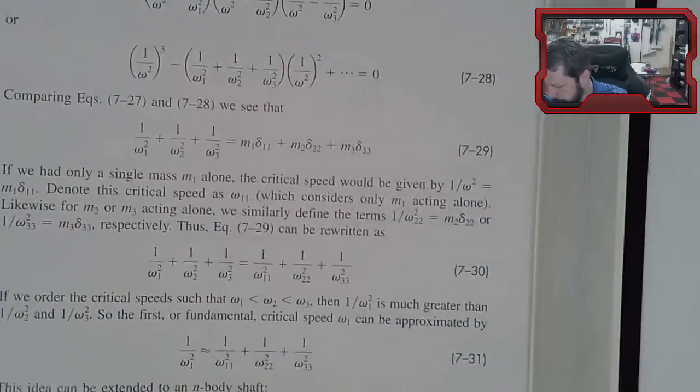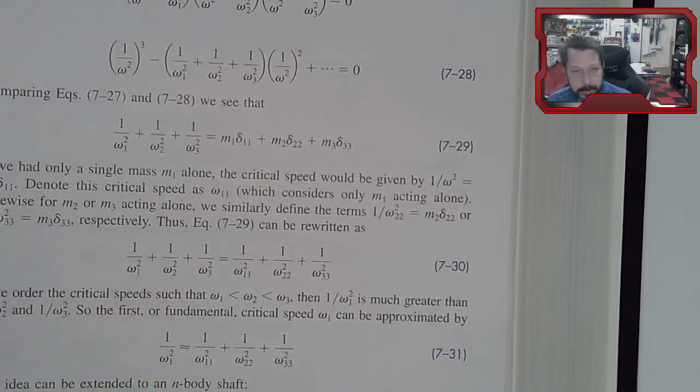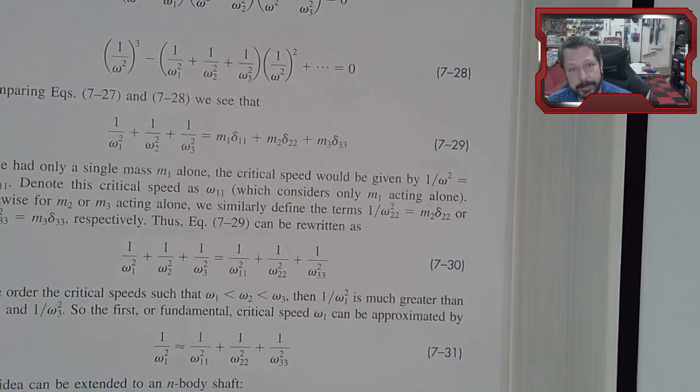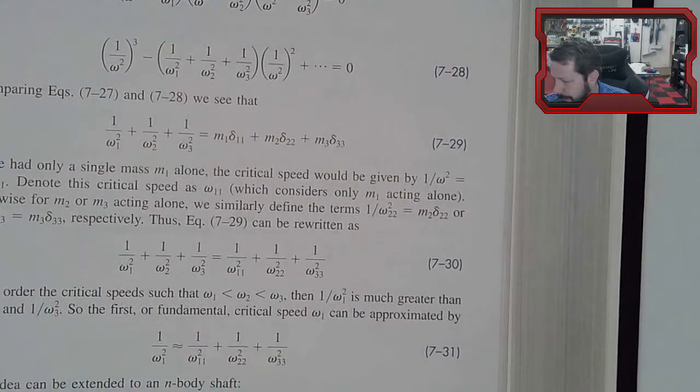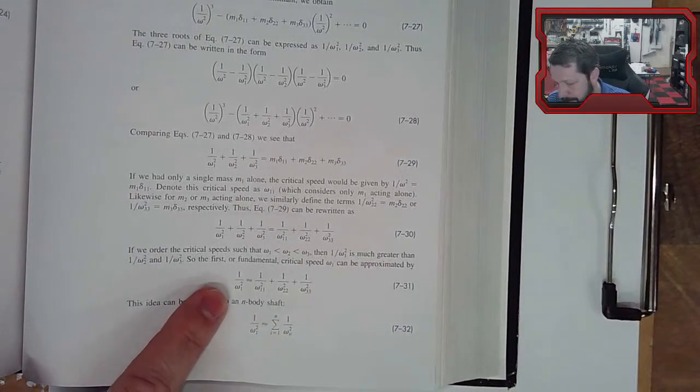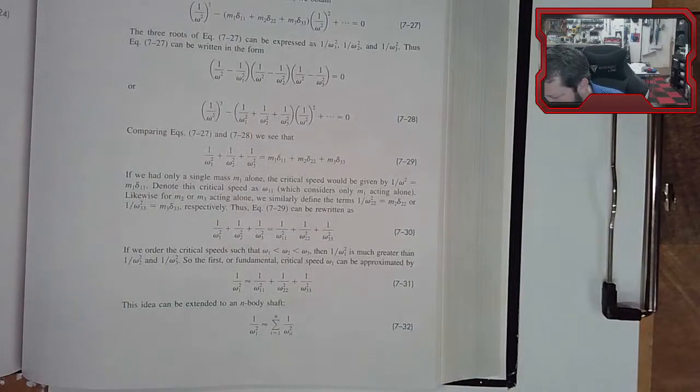Then we're going to go down to these omegas. Now when we did the springs, the critical frequency came out in hertz, cycles per second. These equations are going to give us omega, which are going to be radians per second. So we do have to make sure that we don't accidentally get confused.